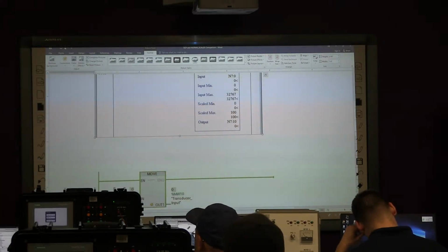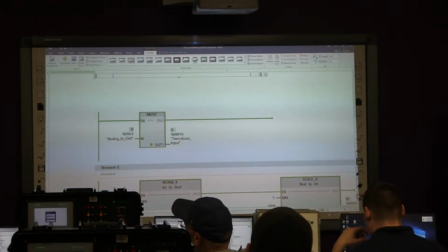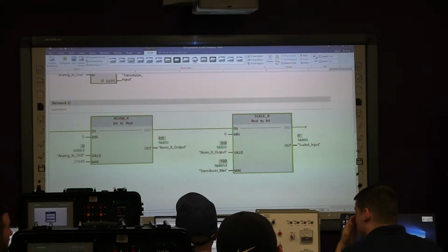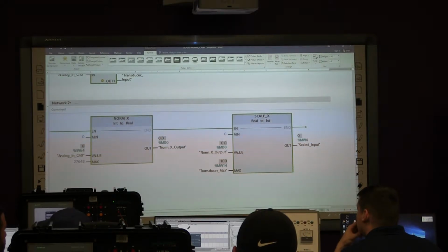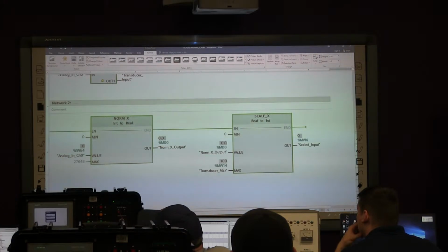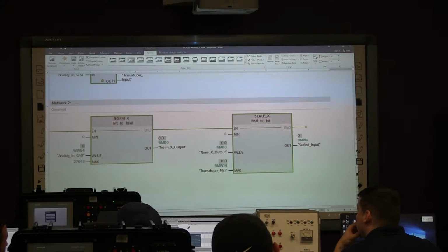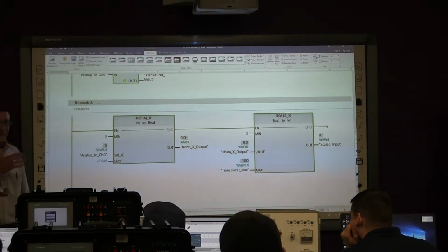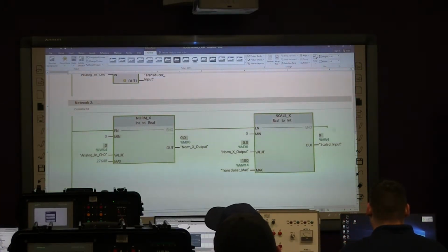In fact, all Siemens analog modules, that's the spec on it. Is that just what they're rated to? Yeah. Okay. They're all 10-bit, 11-bit resolution. So with that in mind, Allen-Bradley's more accurate with that. Yeah. Resolution wise. Of course, you're splitting hairs when you're down to that finite little detail.